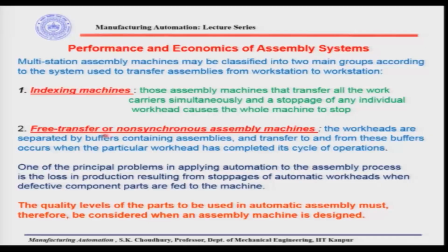Now, in case of free transfer or non-synchronous assembly machines, we do not have the indexing table, and therefore, we have the buffer stock in between. So, if a machine stops, the other machines may not suffer till the buffer stock is filled up or while buffer stock is available.